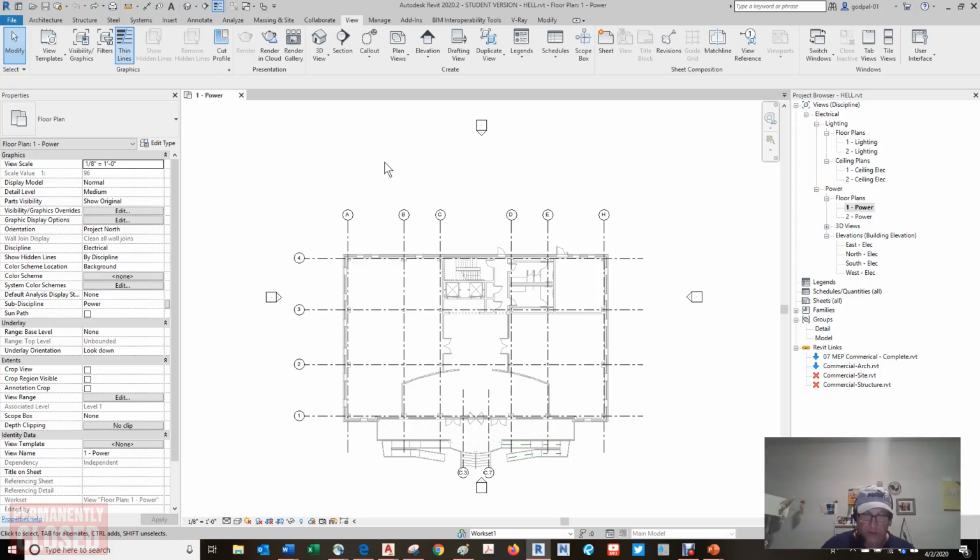Now you can create duplicate views of any of your project views and assemble them in the working space. Zooming in and out is much more fluid and yet limited to the extents of one drawing area. You can create a keyboard shortcut to activate and deactivate views, which is helpful. We could do that. Now, if you decide to tile the views when you work, let's open a couple.